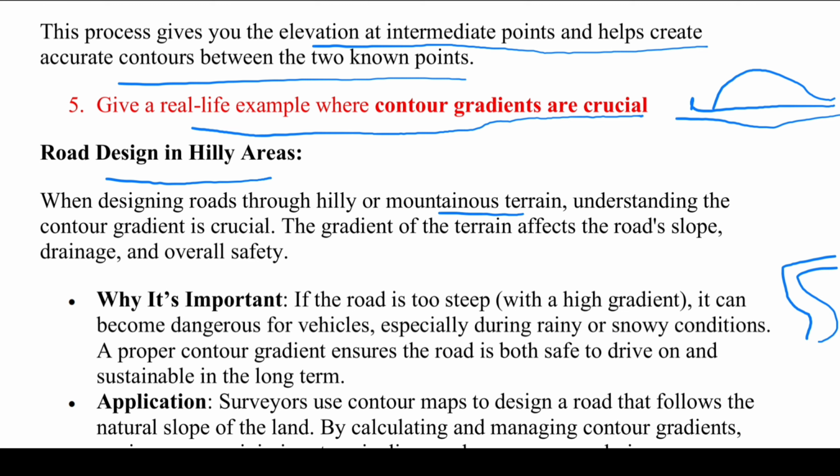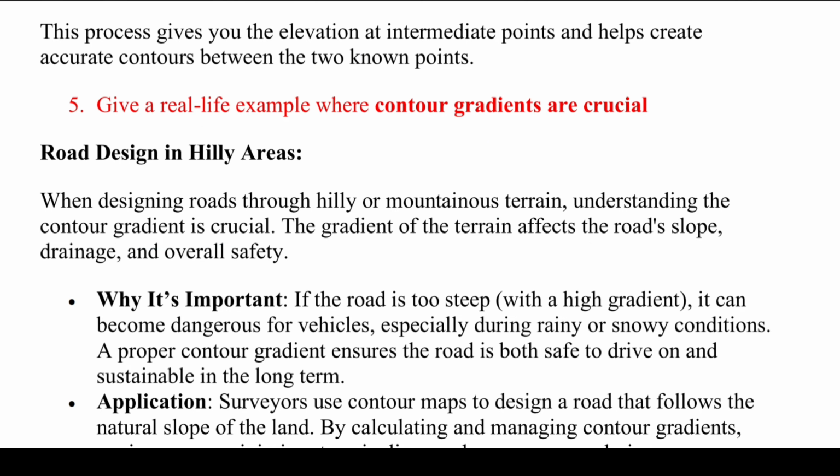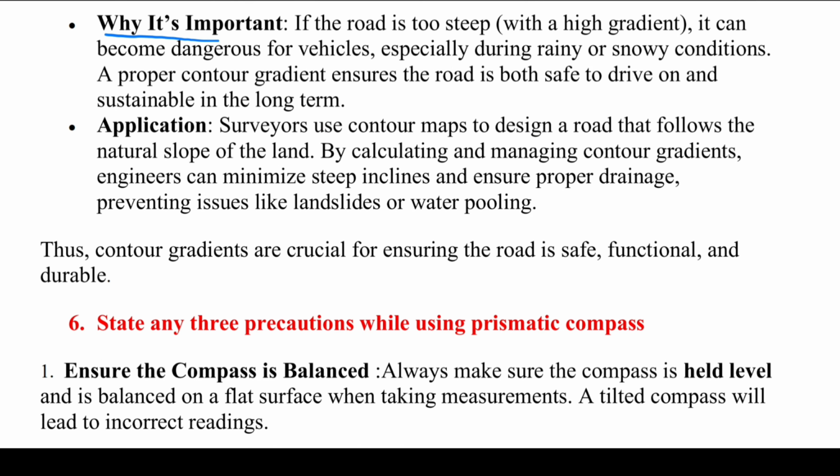So we have to understand that the contour gradient is very crucial. It is very difficult. The gradient of the terrain will affect road slope, drainage and overall safety. Safety also we need to take care of in the construction of road design in a hilly area. With a live example I will explain why it is important.